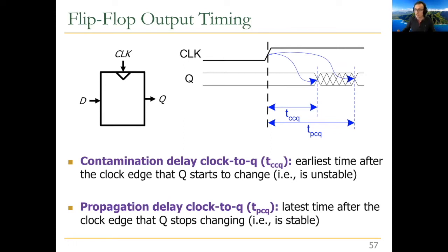And this is going to be important because this is going to affect how long it takes for us to get the Q. Clearly, Q is going to be used, which is the flip-flop output, right? It's going to be used in some combinational logic inside a finite state machine, right? Or as part of your sequential system. So this delay affects when Q is available to you, right?